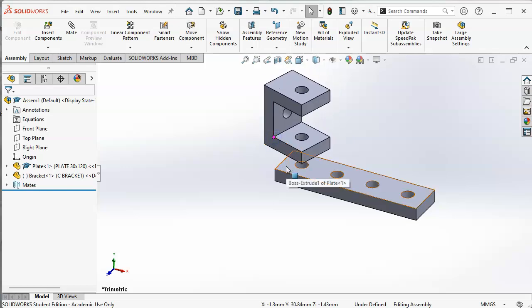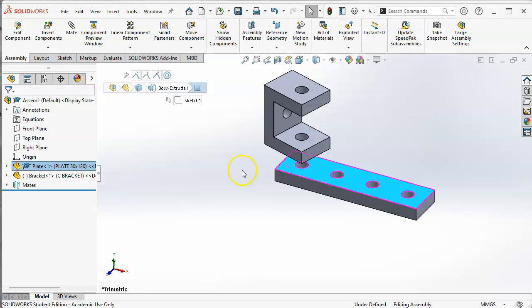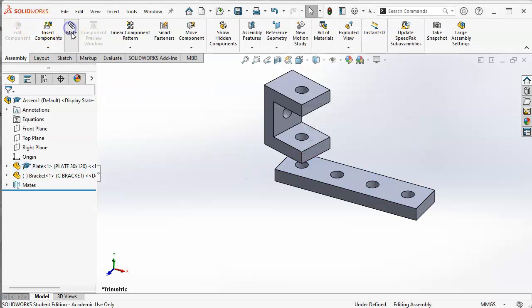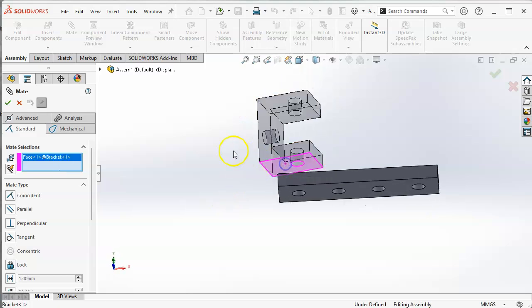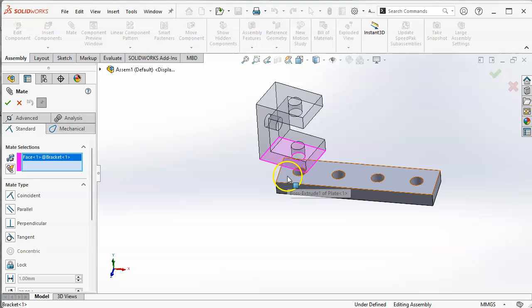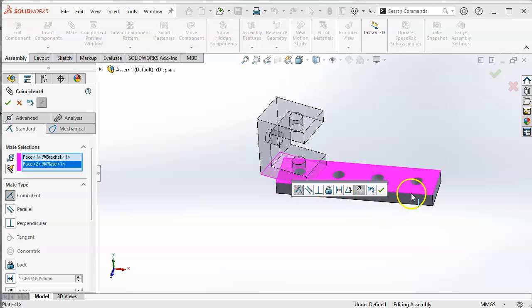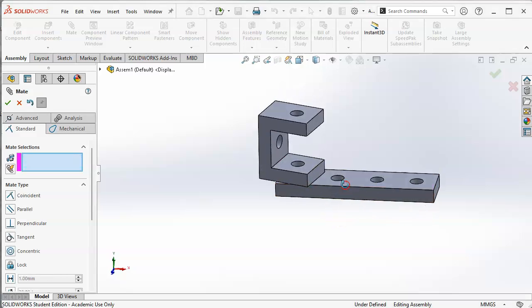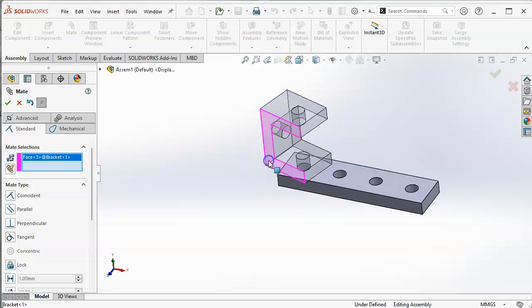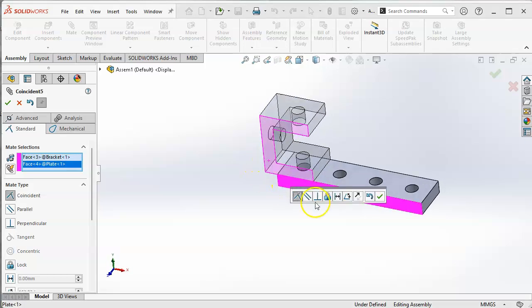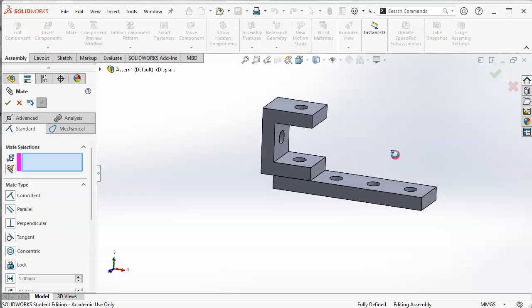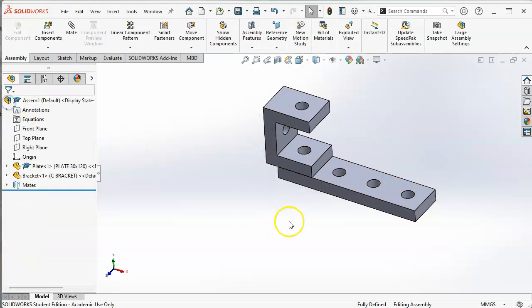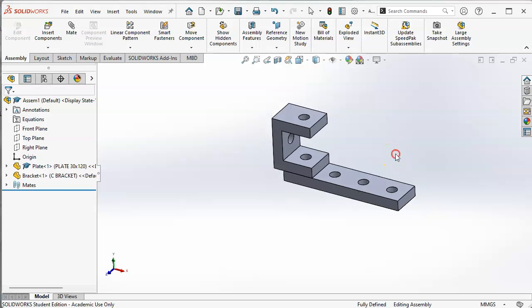All right, so we're going to look at a coincident, and let's do another mate reference with the paper clip, and I rotate over till I can see the face, and those become coincident. And I'm going to start using parallel for some of these, and also make the illustration that if the size changed or something like that, the geometry would update.